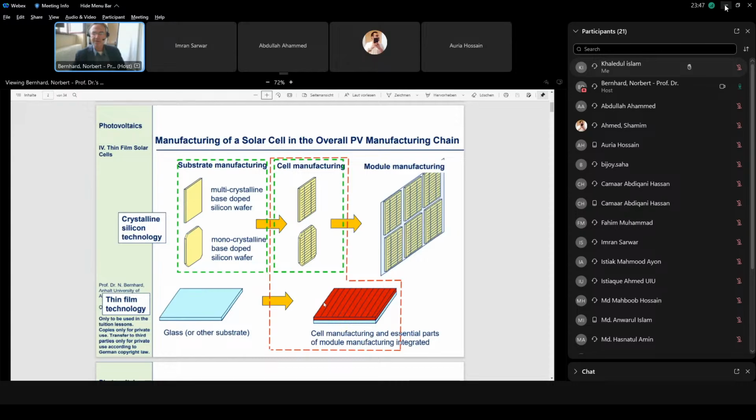Okay, this is just a picture of such a PECVD deposition system, such an industrial system. You see these are quite big substrates. It looks like a mirror here, probably because it is obviously after the metal deposition. And this would be the counter electrode here on the right hand side, and you see also this shower head. I mean, through these small nozzles, the reaction gases are let in.